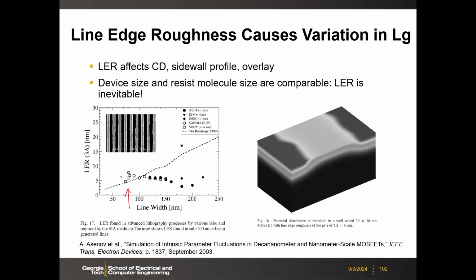So here, this sigma of this LER will always be the same because of the molecular nature, right? No matter how wide the wire is, the edge is always rough by that 2 or 3 nanometer. If your wire is large, like 200 nanometer, not a big deal. But if your wire is small, like 20, 30 nanometer, this 2 or 3 nanometer difference will show up.